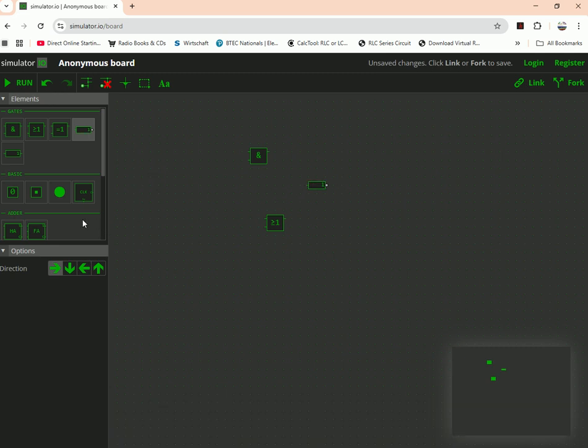And then for the output, we want to have something to combine all these three gates. And let's go for an OR gate. And we want three different inputs. And if you look at the input count, you can see this here. So I can increase it to 3. And I'm going to just click here on the middle. And I've got my three inputs.